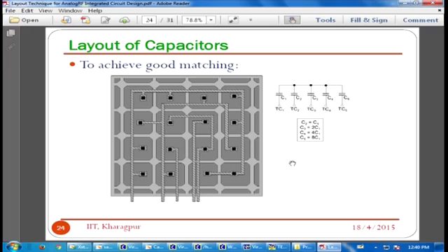That's why if you look at the layout, there is a huge patch which is designated as the capacitors. Not as a single isolated block like an inductor, here, here, here. It's a squarish patch, where all the interconnected capacitors provide you the required capacitance. So you can have less variation of the capacitance. This way no area will be wasted, and it's a compact square format.